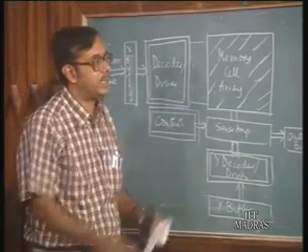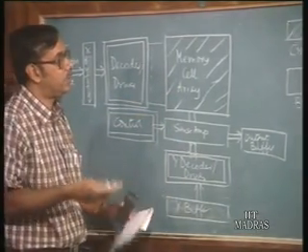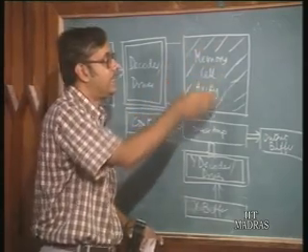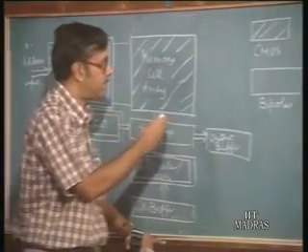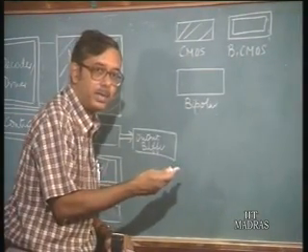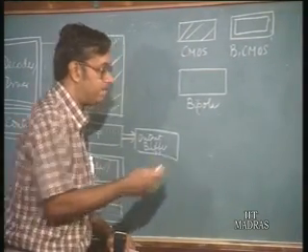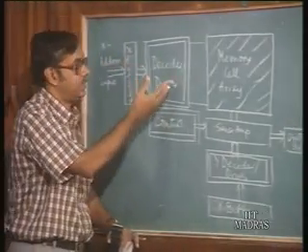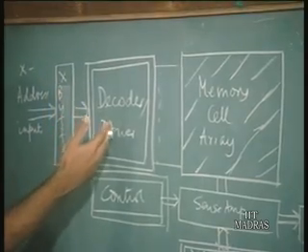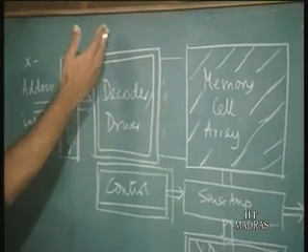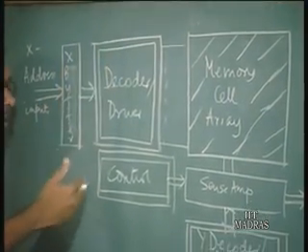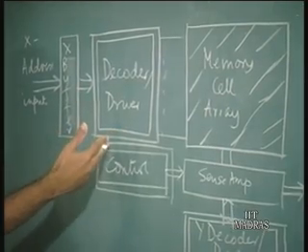Okay. So, what is done is you have negative voltages, but it is still in CMOS type of levels, that is, suppose you want a 5 volt memory. Okay. So, this is converted, say in a BiCMOS, you know that the output is going to go from VDD minus VBE to VBE, which is the lower level.